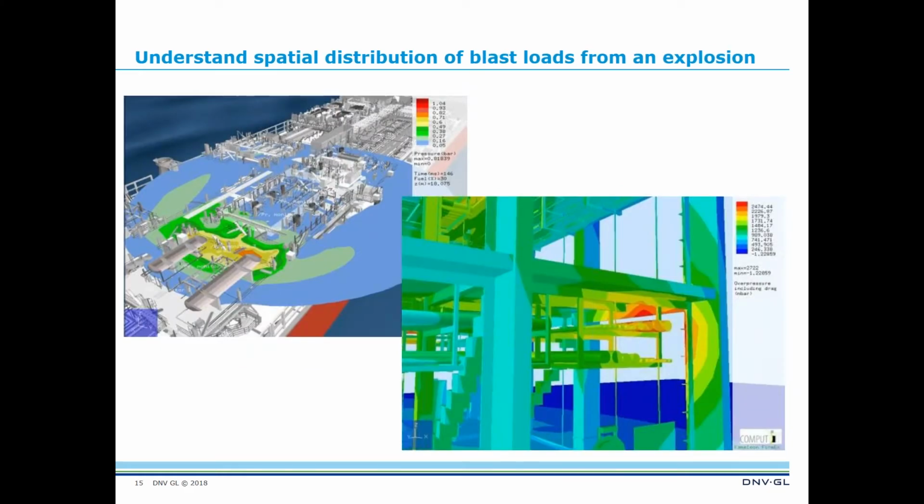Continuing with explosions, again from an FPSO, an explosion simulation. To the left, you see some contours of overpressures during the explosion. And to the right, this same type of footprint on the topside structure, now showing the overpressure, including drag force on the different members of the topside structure.